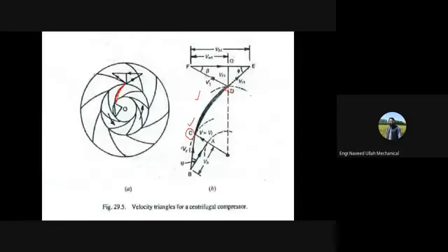And then they are saying that now we have to have some nomenclature. So now let us draw the velocity triangle at the inlet and outlet tips of the blades, as shown over here. Obviously we need to draw the velocity triangle at inlet and exit. Inlet is basically this inner tip, this is the whole blade. So this is the inner tip and this is the outer tip. We draw the velocity triangle at the inner tip, so this will be the inlet velocity triangle, and at the outlet tip, this will be the outlet velocity triangle.